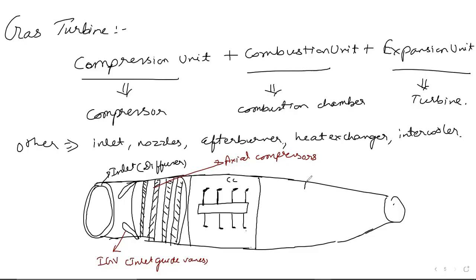After that, there is a turbine. So in the turbine, what happens? Just the opposite of it. Again, here stator then rotor, and here rotor then stator will be there. Although it will have fewer stages. If the compressor has, say, 14 stages, it will have 7 to 8. So this is basically the turbine. First, the high velocity gas whose velocity has been decreased but pressure increased, this high pressure gas goes into the combustion chamber and is heated. Now this gas is at high pressure and high temperature, both. Then it is going to the turbine.